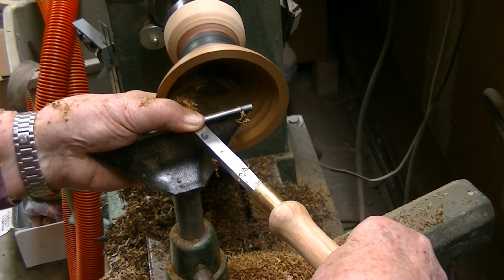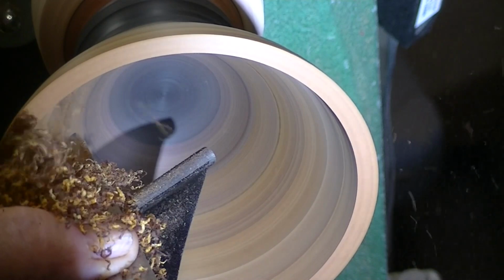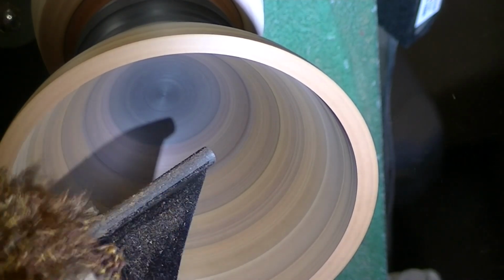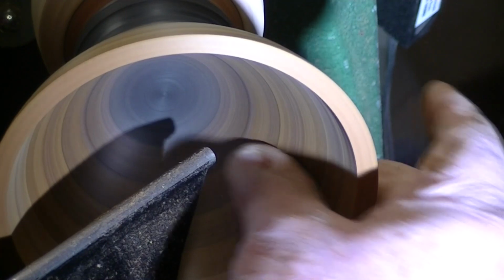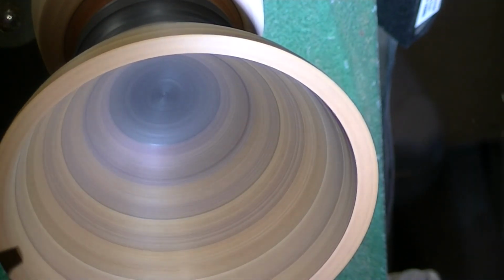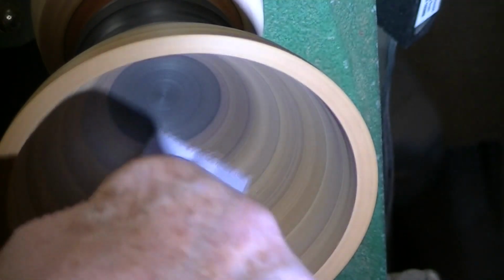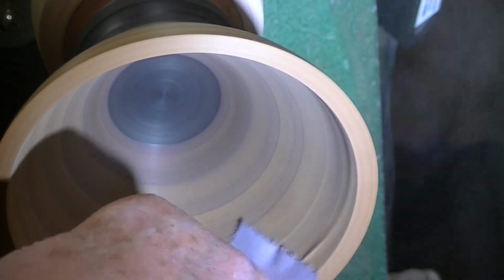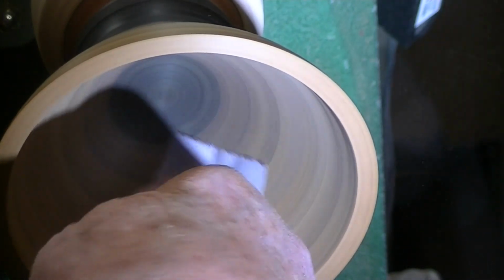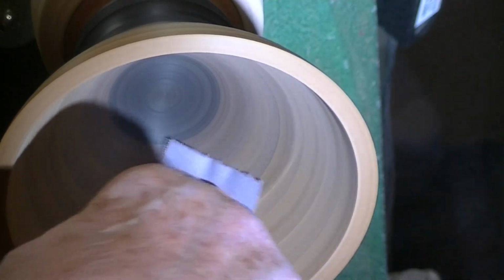I am going to negative rake scrapers that are much more severe in their angles, and you can see the cuts going on inside here. I just wanted you to be able to see how it looks as we begin to clean it up towards the very end. I want that inside to be smooth and perfect. I also want the inside edge wall to be parallel with the exterior wall as best I possibly can. Once I've achieved that, a little interior sanding, get it cleaned up inside. And that piece is just about ready to go.